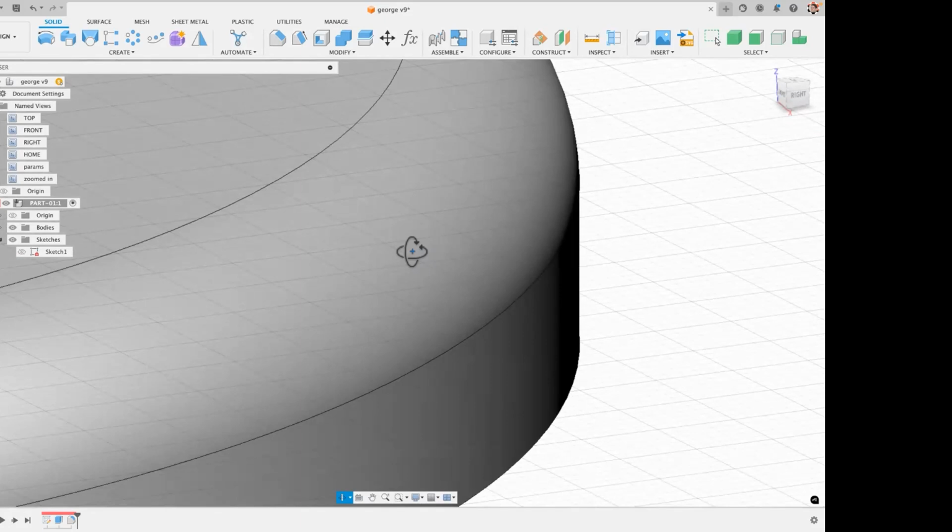Oh, okay. If you didn't do that and you just grab the orbit tool, like makes sense. I'd be flying all over the table. That's right. If you click and drag, it goes crazy on you. And it doesn't tell you this. You have to go to the manual or something. So click and let go is going to set that as your pivot point. Okay. And then you go.